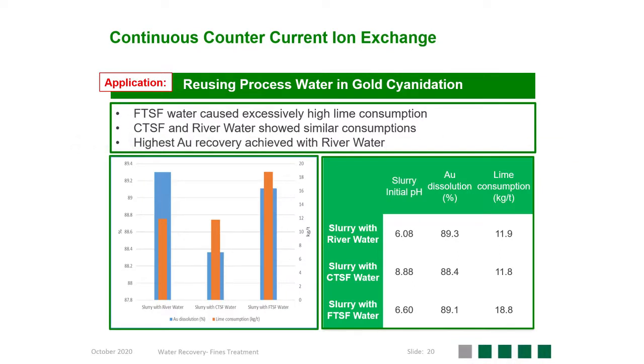These higher recoveries in both the case studies can be attributed to the reduced contaminants that is present in the process water. While gangue minerals are insoluble in cyanide solution, some metallic minerals such as iron, copper, etc. are soluble and deprive the solution of its oxygen and cyanide, consequently reducing gold recovery.